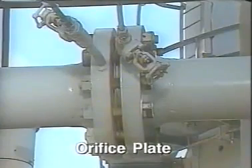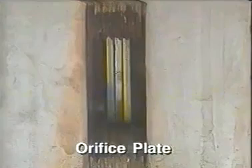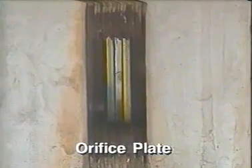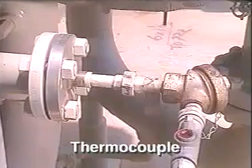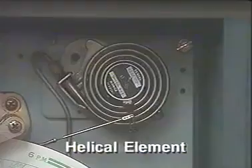These instruments are usually called primary elements or sensors. The devices in this group that are installed directly in process flow lines and process vessels are usually referred to as primary elements. This orifice plate is a primary element for flow measurement. A thermocouple is another type of primary element. It's used in making temperature measurements.